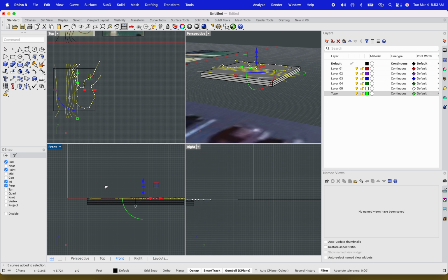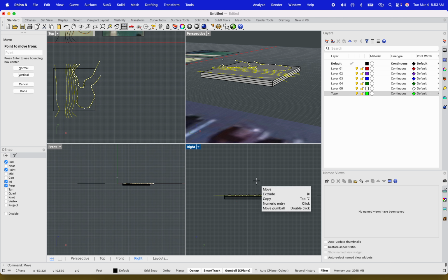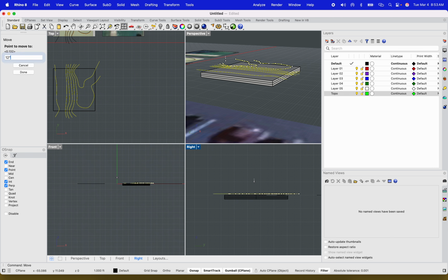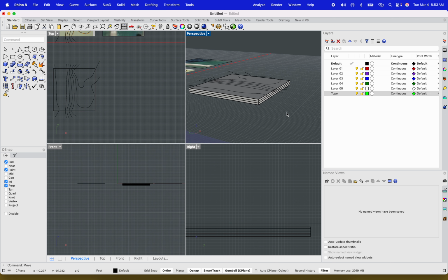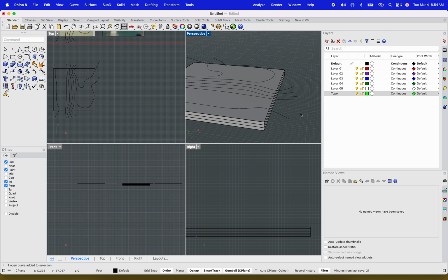So I'm going to use that line, make sure that I'm in the right spots. It's looking pretty good for the view that I need. Go ahead and move 12 inches. I might want to hit ortho, especially if I want to keep it absolutely straight. And in this case, I definitely do. So I'm going to make that one 12. And then really, that one's at the right spot now. So let's get the next one.